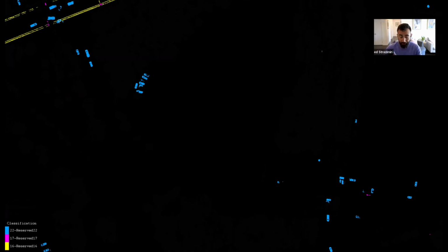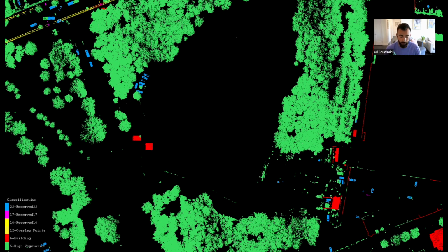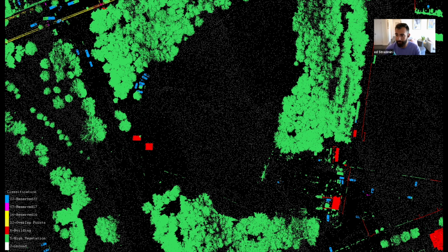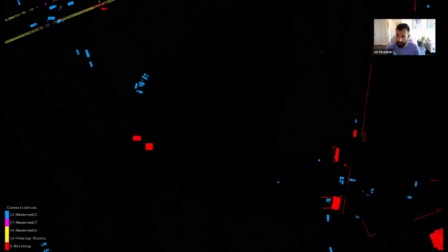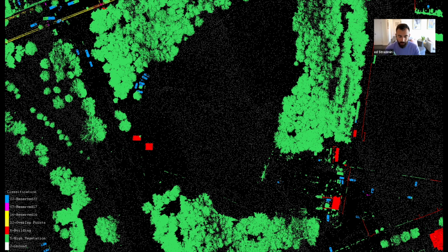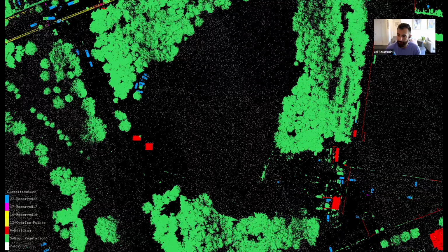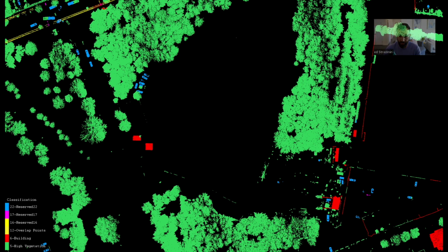Yeah, well, generally, the thing that most LiDAR users are after when they're planning a mission with LiDAR is the terrain. They want to get an understanding of what the terrain in the area is, right? So a topographic survey, essentially. That's where this classification starts. That starts you on that path. So we need to pull out the ground points, the points that represent the mean elevation of the ground across the area. So once we have those points classified, then we can start working with those clouds.